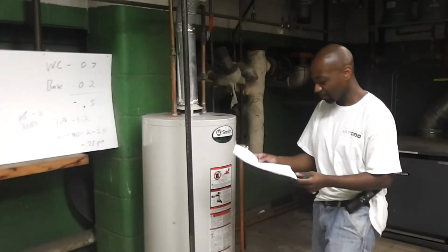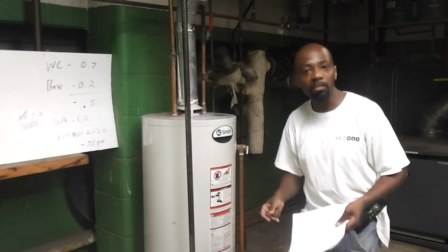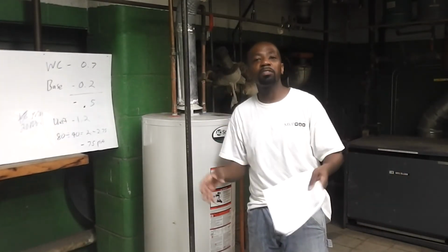So even this combustion appliance is still working okay. This combustion appliance is working properly. It looks like we're still good. So the next, that was spillage passed, draft passed. The last thing that we're going to do is the undiluted CO.